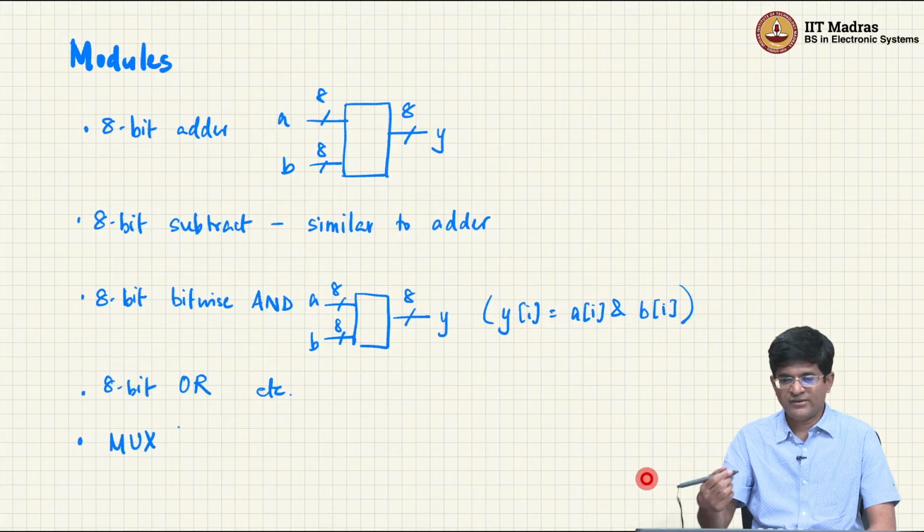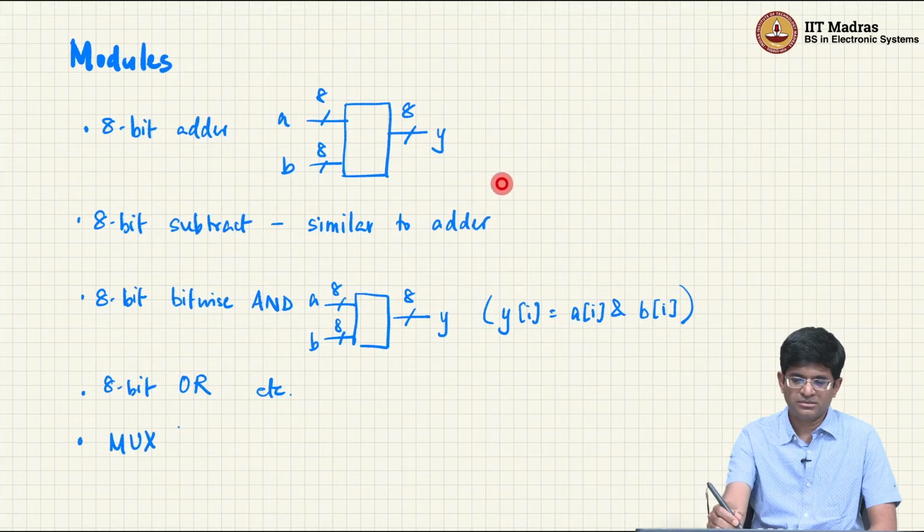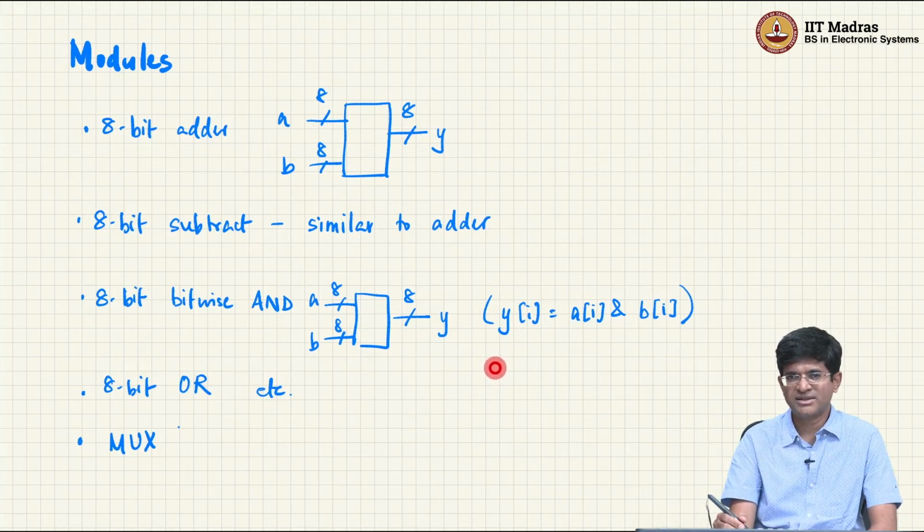So now let's see where we are. We have these modules, we have an adder. In the same way as an adder, we could define a subtractor, where I take 2 inputs and do B minus A. In practice, this doesn't normally happen. What is actually done is we use the trick of 2's complement and say that a way of subtracting a number from another is to complement it and add. 2's complement has some very nice properties in terms of how you can use addition to perform both addition and subtraction. So the hardware is much simpler that way, but for argument's sake, let's assume I have a different module that performs subtraction.